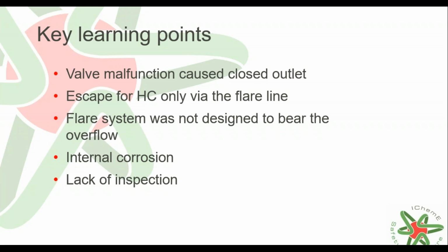The flare system was not designed to cope with this excursion from normal operation, and due to liquid breakthrough at the FCCU flare knockout drum, a failure occurred in the outlet pipe. The investigation revealed that internal acidic corrosion also contributed to the pipeline rupture. Apparently, the company didn't inspect the weakest points of the pipeline, which were exposed to corrosion.